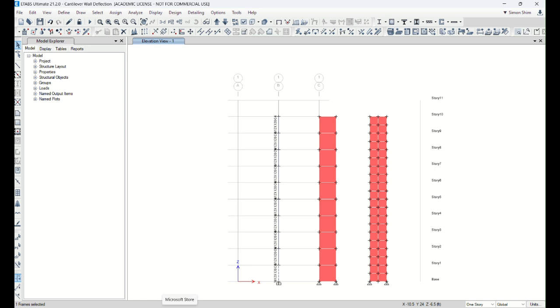We'll see. Now, how about the shear force diagram along this wall? What should the shear force look like? Constant shear force, 100 kips all the way down, right? We're going to get into that. You don't need to analyze it. You only need to know it. You should be able to know 100 kips applied all the way through this entire length. We're going to double check with this model.